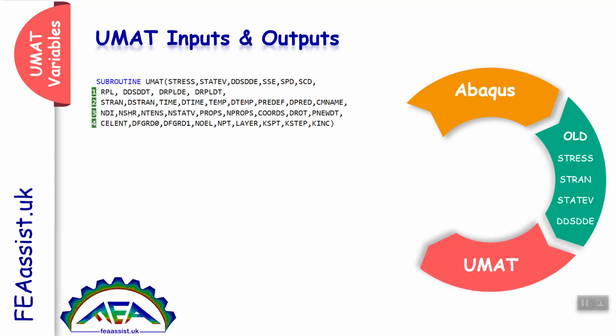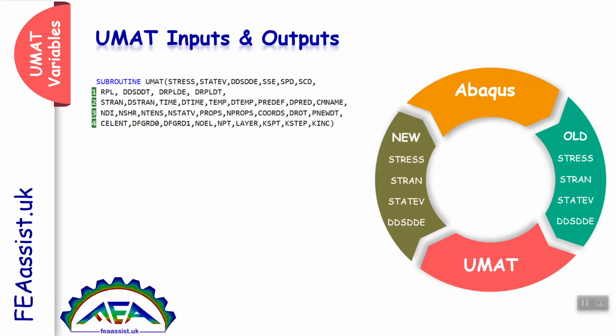In the VUMAT, we need to write some equations based on our constitutive behavior to recompute all these variables and return them back to Abaqus. This is how Abaqus and VUMAT interact with each other, which is necessary to write a well-working VUMAT.